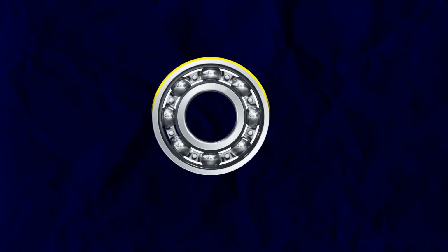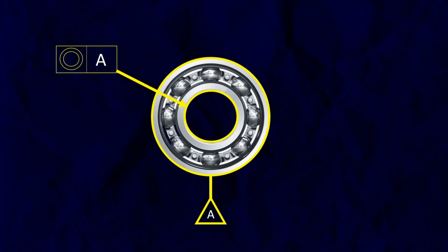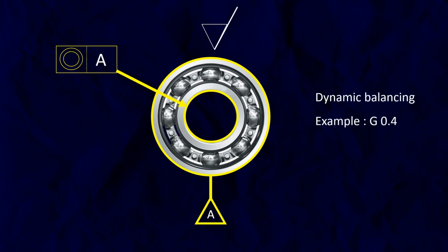So what is the main purpose or main advantage of using high tolerance class bearings? So the first advantage is the dimensional accuracy. And the dimensional accuracy is not only about the tolerance accuracy in ID, OD or width. High dimensional accuracy bearings also give us geometrical accuracy, like the position accuracy of the inner race with respect to the outer race. Also the high grade surface finish and good dynamic balance allow the bearings to achieve high speeds, super speeds like 50,000 RPM. Could you imagine? And all these things apply to almost all types of rolling element bearings.